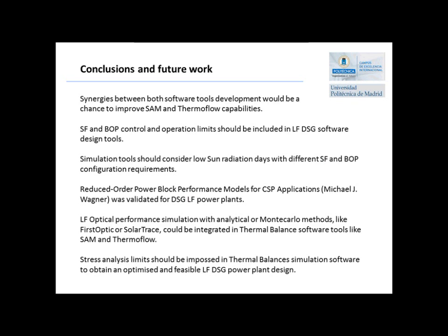Linear Fresnel optical performance simulation with analytical or Monte Carlo methods like FRED optic or SolTrace could be programmed in thermal balance software tools like SAM and Thermoflow. A stress analysis limit should be imposed in thermal balance simulation software to obtain and optimize a feasible linear Fresnel direct steam generation power plant design.